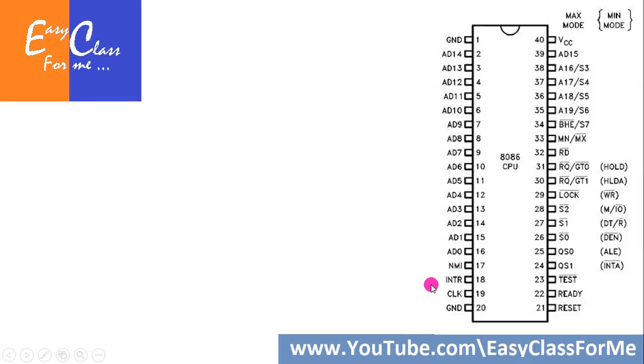So what we are going to do is we will first start with the power supply. What type of power supply is needed for this 8086 microprocessor? So you can see that at pin number 40 you can supply VCC, which is plus 5 volt, and it can have a toleration of plus minus 10%. So a plus 5 volt DC supply is necessary, and here there are 2 ground connections. You can see them at pin number 1 and pin number 20. So there are 2 ground connections. What is the need for supplying 2 ground pins?